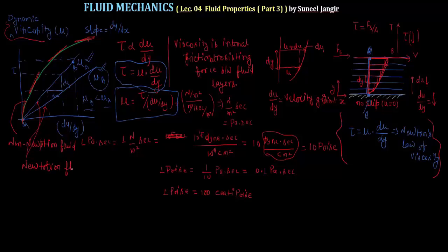Newtonian fluids, like water, oil. Most of the engineering fluids fall in the category of Newtonian fluids. Some hydraulic fluids, water, and all this. And there are very particular different brands for these types of fluid. Like milk, sewage sludge, chocolates, these types of fluid do not behave according to this law. They have a different nature. The slope is variable. These are termed as non-Newtonian fluid.